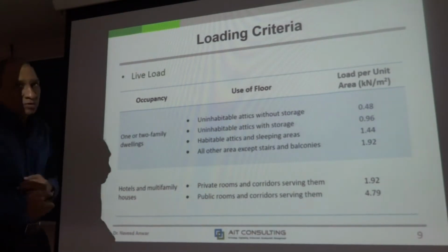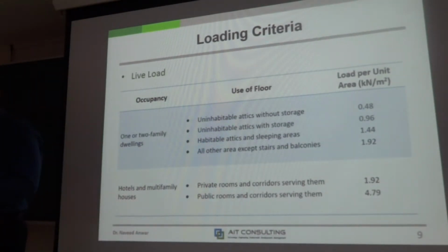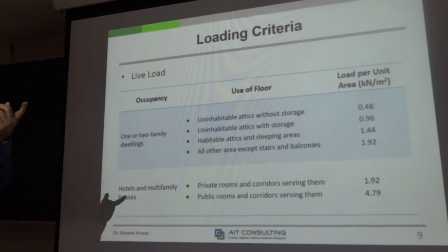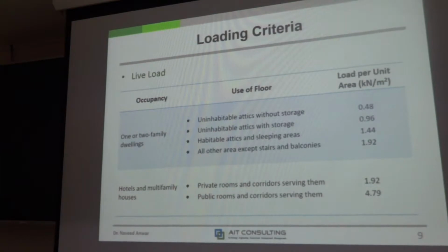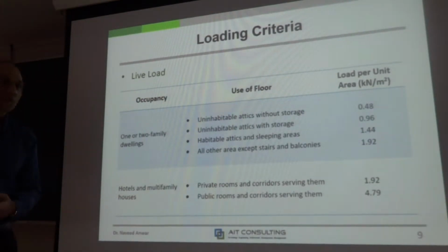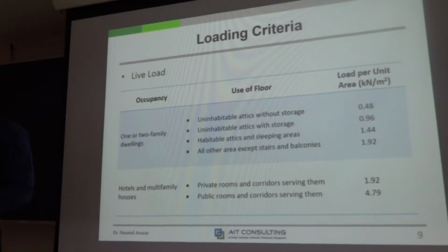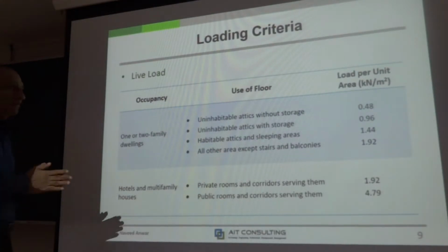Live load. This is quite complicated. Why? Because of the usage. Classroom, sleeping quarters, dancing floors, gymnasiums, library, depends on the use. That's why in advanced countries, in the USA and other places, every room has a plate indicating this room is designed for this much live load. This building is designed for that many persons. Some hotels write this building is designed for 489 persons, not even 490 or 500, 489, because that's what they calculate. So if it is more than that, then responsibility shifts to different people and so forth. But we don't have that practice here.